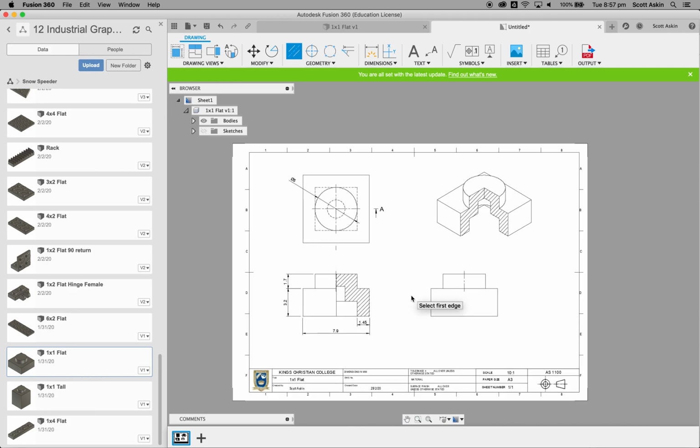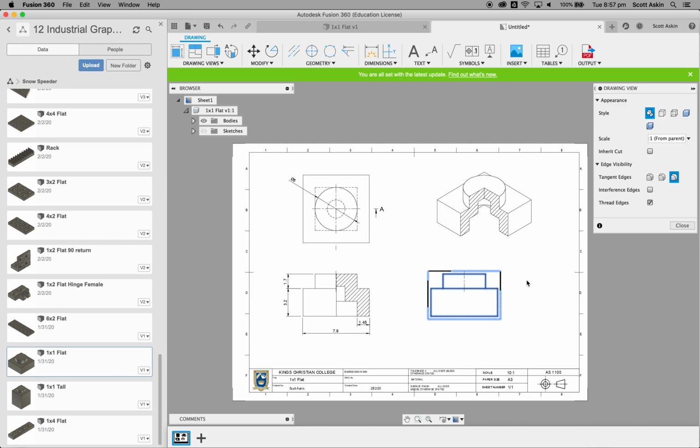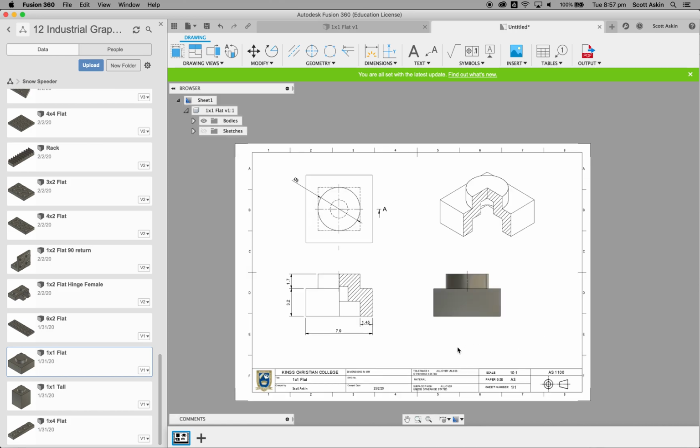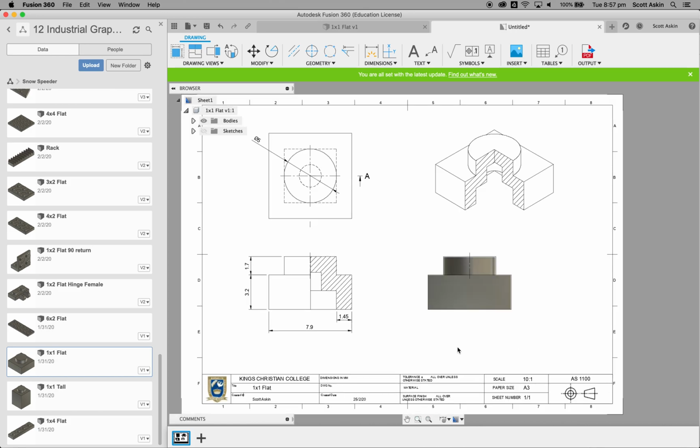All right, that looks pretty good. Front view, top view, right side view. We probably don't really need this view, but we'll put it in there. And what we might actually do, why not? You're going to jump out of the Centerline and double click on this view, and I'm going to turn shaded on. And I wonder if that's going to help the viewer understand that much at all. I'm not too sure. I'm just going to leave it like that. We'll sort of see how we go. All right, hit save, of course.